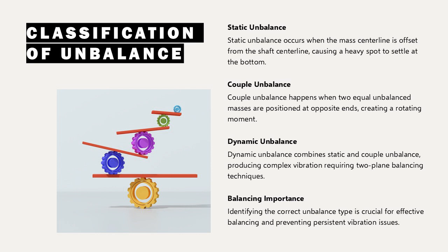Dynamic unbalance is the most common condition encountered in real machines and represents a combination of static and couple unbalance. Each type of unbalance produces distinct vibration characteristics and requires specific balancing techniques. Understanding these classifications is essential for selecting the correct balancing approach, whether single-plane or two-plane balancing. Failure to identify the correct type may result in ineffective corrections and persistent vibration problems.